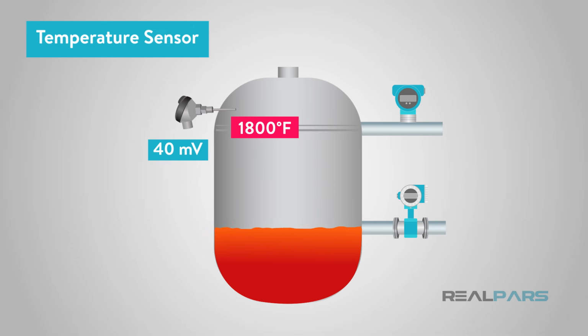So far, I took a big first step, which was the transformation of temperature into electrical signal. Based on different sensor technologies, this signal may have different ranges, and for industrial applications, I need to have my signals limited to some universally accepted electrical signal ranges.